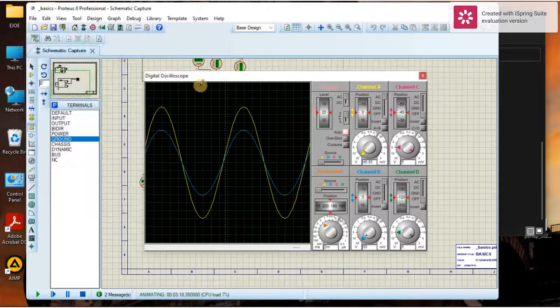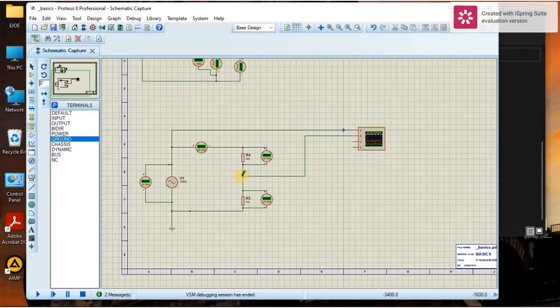Okay, but now that is only the voltage at this point, the voltage between this point and earth. If we want to get the voltage between this point and this point, then we just subtract, because this is between this point and earth.